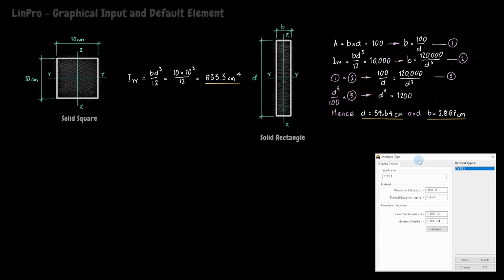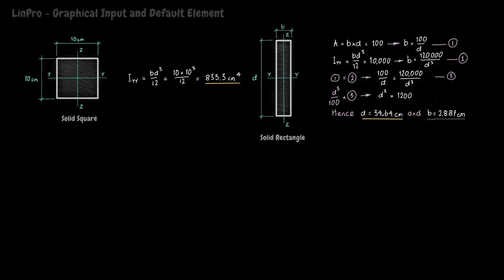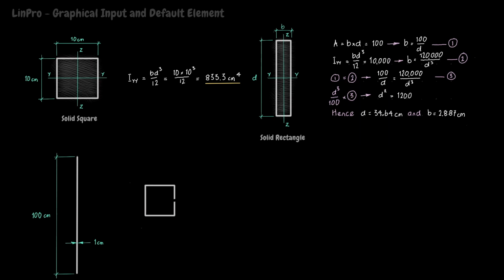At this point, Dr. Jim stopped to have a well-earned cup of coffee, and he got to thinking that a sheet of steel 1 centimetre thick and 100 centimetres high would have the correct cross-sectional area. His next thought was that sheet of steel could be folded to make a 25 centimetre square hollow section. Genius or what? Of course, the section does not have to be a square. For example, it could be a 20 by 30 centimetre rectangle.